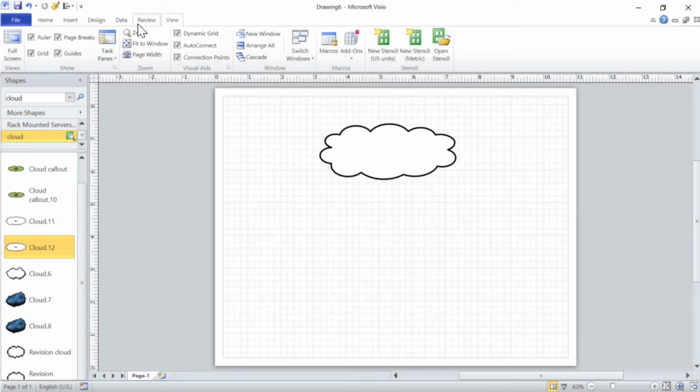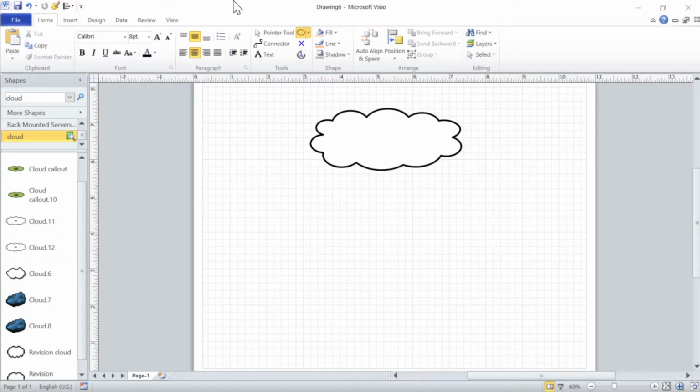So we needed some circles. To get the circles, go up here to the drawing tool, pick ellipse. Now to draw a perfect circle, you want to get the cursor right on the junction on the grid. You want to get it right on the corners between squares.